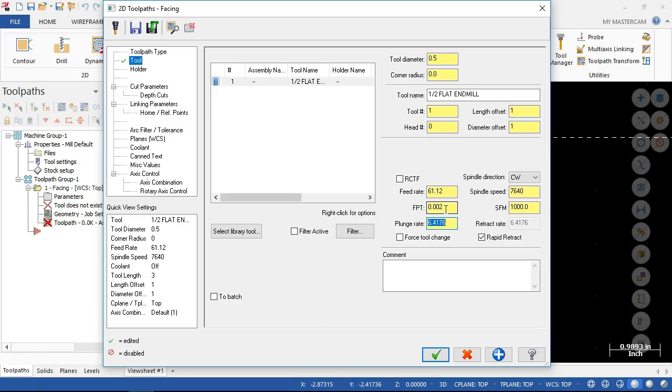All right, so when I typed in the 2,000s per flute, we'd have to look at the definition. That's probably a two flute, maybe a 3-flute. 61 inches a minute, that's pretty aggressive for a very start. All right, but it depends on, again, are you doing the setup and are you the operator, or are you handing this off to somebody?